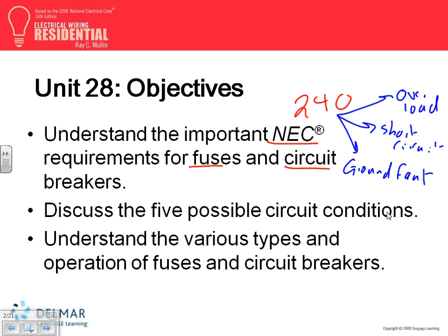In terms of multiplier, if my normal current is I, then the overload would be probably from 1 to 2 times I. That's an overload condition. Does that make sense? If your current is 10, an overload condition would be between 10 and 20. So a multiplier of 2 means you double the current. That's an overload condition.